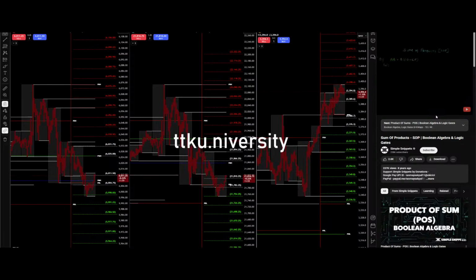Okay, so I have written the question on the blackboard. Now as you can see, this is not a standard form, that is, this is not a sum of product expression. Since we have brackets involved, we need to open up these brackets. So here's the solution. If there are brackets involved, we first need to open them up. Now how to open up these brackets? We have seen the distributive law wherein we open up the brackets. So the solution would be A, B, or we need to take an AND operation between B and C and D, and we need to take an AND operation between these with a sum or operation in between. So the equation would be